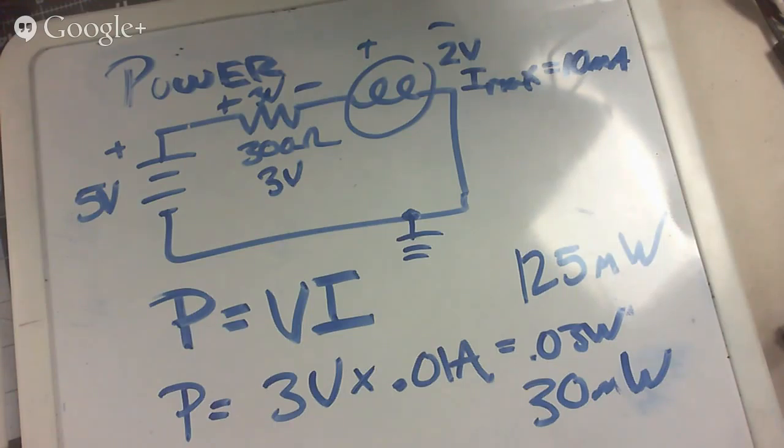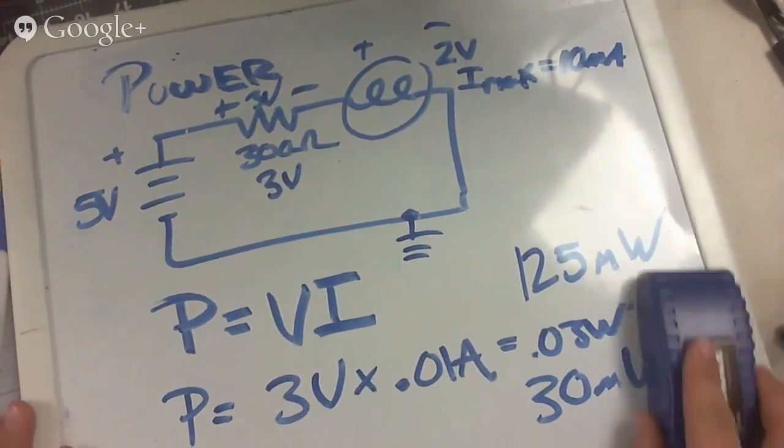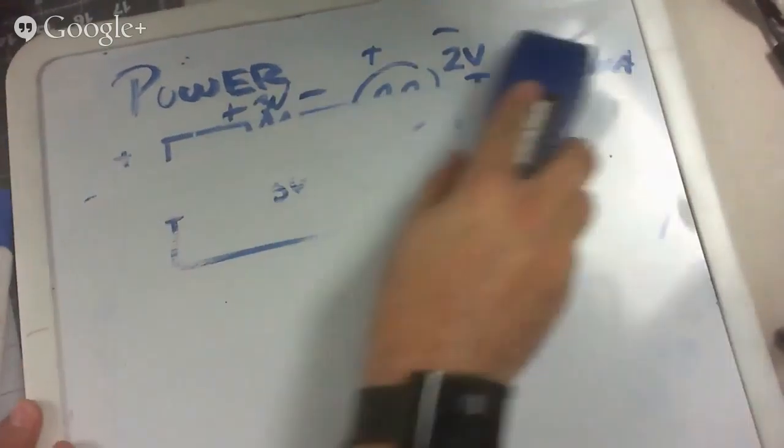Again, when you size components, you've got to make sure that you take into consideration the power, the voltage, and the current. Sometimes you want to rush through, you calculate the size of a resistor you need. You just got to take the extra couple seconds and also calculate the power that you're expecting to dissipate. Okay, so that's the easy stuff. That's the fun stuff.